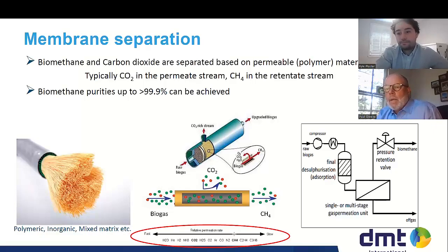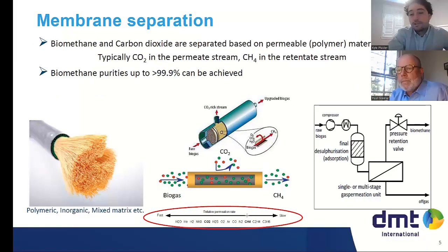Yeah. So what are the conditions that you're trying to get to before the membrane, as far as things like dew point and pressure? What are the optimum feed conditions you're trying to engineer to? Yeah, so dew point, you need to get pretty much all the moisture out. Rule of thumb would be negative 40 degrees, but the key here is just nothing condensing within the membranes. And when you're at a high pressure after the compressor, that can happen. So that's why we have that final compressed gas treatment where we get all the moisture out of the gas.